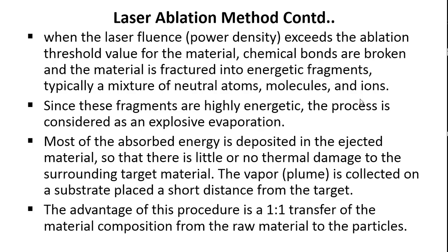So when the laser beam focuses upon this target material, due to the laser fluence, the laser power density, when it exceeds the ablation threshold value of the material, that is the threshold value, then when the laser fluence power density, fluence means power density, the laser power density exceeds the ablation threshold value for the material, the chemical bonds are broken.